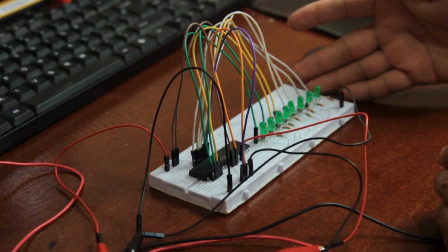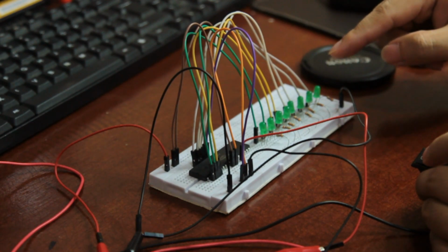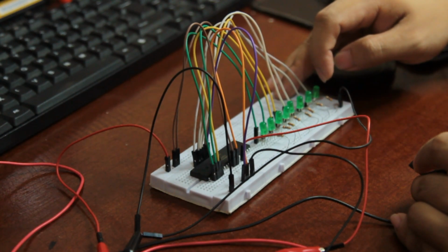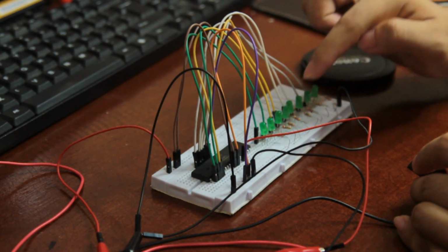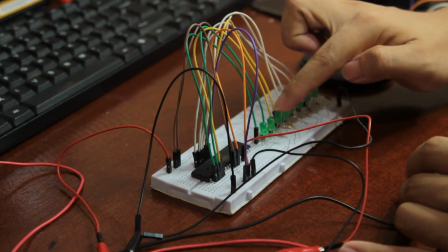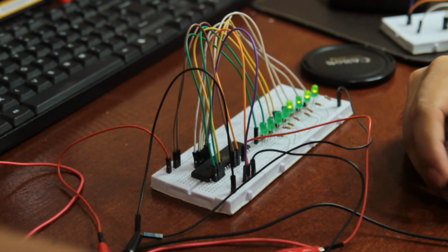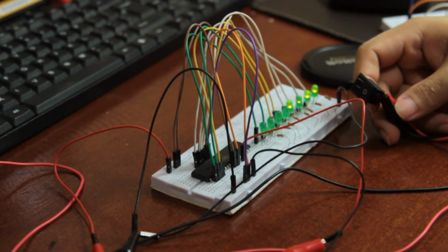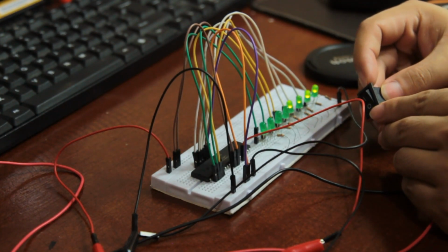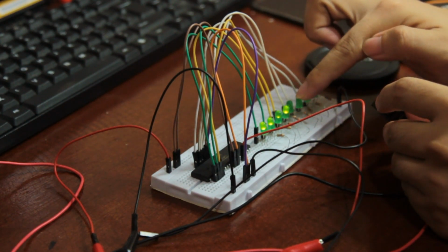So we have here a sample circuit with 8 output LEDs. With the concept of PIC microcontroller programming, if I set my digital input to 0, the last 4 LEDs will light up and the first 4 LEDs are off. However, if I change my digital input to 1, the first 4 LEDs will light up and the last 4 LEDs will turn off. So let's test it. Through the switch, it commanded the microchip to have a digital input of 0. However, if I change my digital input to 1, the first 4 LEDs turned on and the last 4 LEDs turned off.